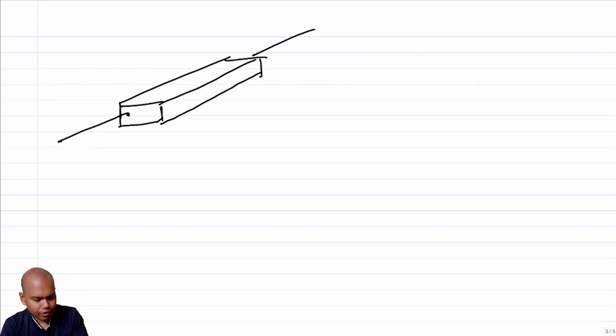So naturally, every piece of metal has a resistivity associated with it. And generally, in many RF processes, the top metal layer is copper, and there is a certain amount of resistivity associated with it. It's typically of the order of 50 milliohms per square. Now, what does the definition mean? If you look at a piece of metal, what are the dimensions that are in our control? When I say our, I mean the circuit designer's control.